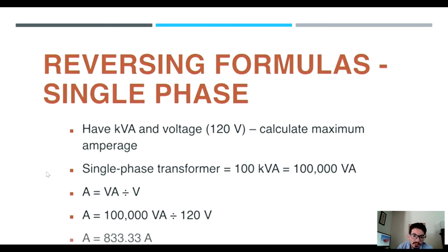Before, we were using the formula to find the size of the transformer if you're designing the application. If you're mounting the system for a particular setup and designing the control panel, you choose the transformer. In this case, for example, they're calling you to provide maintenance on an application. Then what you need to do is check the voltage, which is usually provided by the system, because motors tell you the operating voltage. So that is a good rule of thumb.